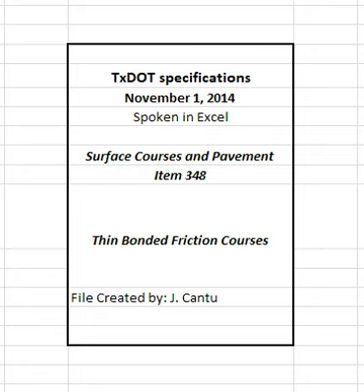If the engineer's test results are pending after 2 working days, conditional approval of JMF1 will still be granted within 2 working days of receiving JMF1. When the engineer's test results become available, they will be used for specification compliance. Produce a trial batch after the engineer grants conditional approval of JMF1.